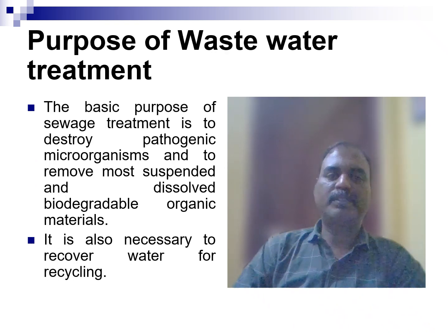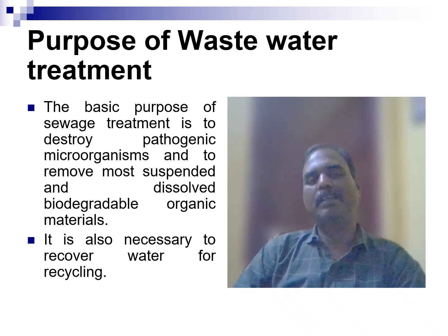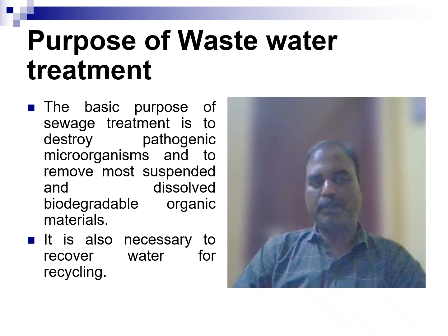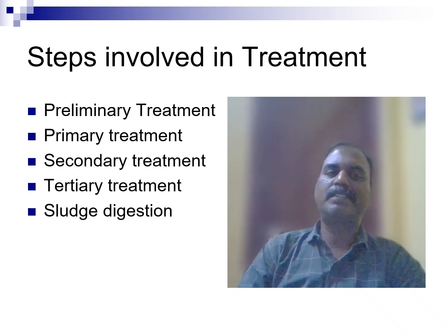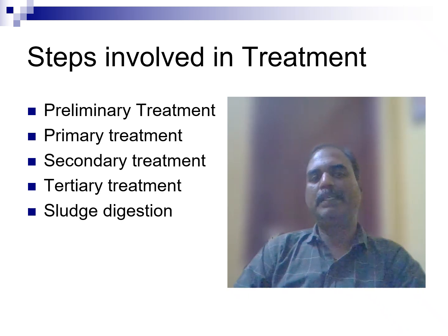What is the purpose of wastewater treatment? The basic purpose of sewage treatment is to destroy pathogenic microorganisms and to remove most suspended and dissolved biodegradable organic materials. It is also necessary to recover water for recycling purposes. What are the steps involved in treatment? Preliminary treatment, or pre-treatment, primary treatment, secondary treatment, tertiary treatment and sludge digestion.